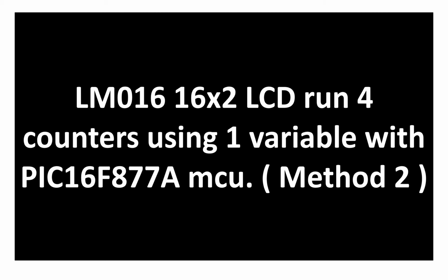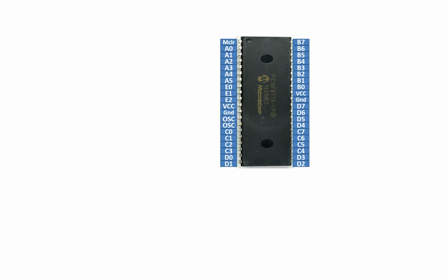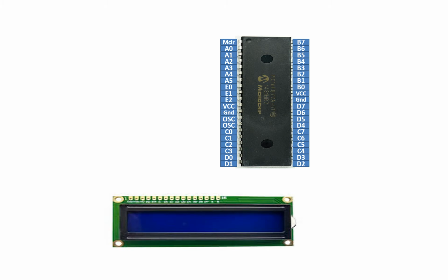So let's get started. Let me first show you how you can connect the LCD with the PIC, and then we will fetch the files from the previous video, and then we will edit them for this technique. So guys, this is our PIC16F877A microcontroller having 40 pins. It's a DIP version. This over here is a 16x2 JHD LCD, also known as LM016.